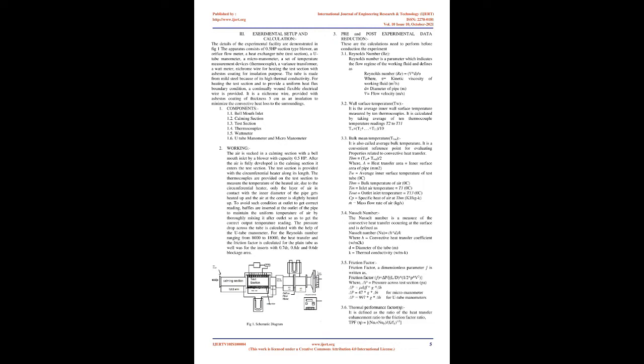2. Active techniques. 2.1 Mechanical aids. 2.2 Surface vibration techniques. 2.3 Fluid vibration. 2.4 Electrostatic fields. These techniques are more complex from the use and design point of view, as the method requires some external power input to cause the desired flow modification and improvement in the rate of heat transfer.